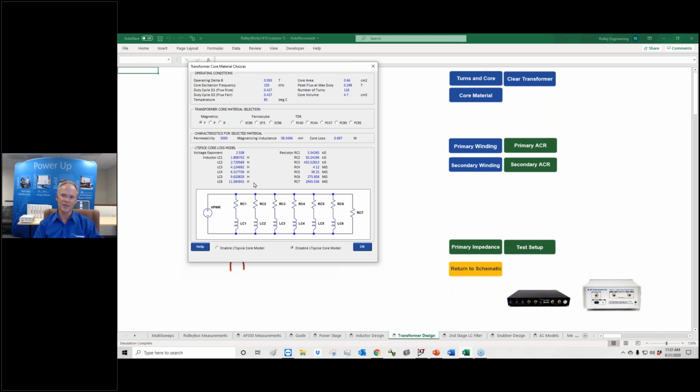So you've got 500 volts up to 700 volts being applied to this, so obviously you're not going to have big resistors in here. But this is the dual of the winding loss model. It's almost like a fractal network, not really, but it's a repeated network. And at different frequencies, different values of resistor kick in to predict the core loss for you.